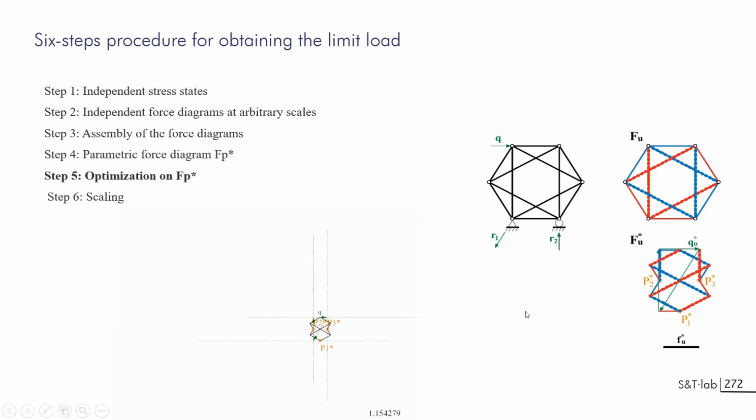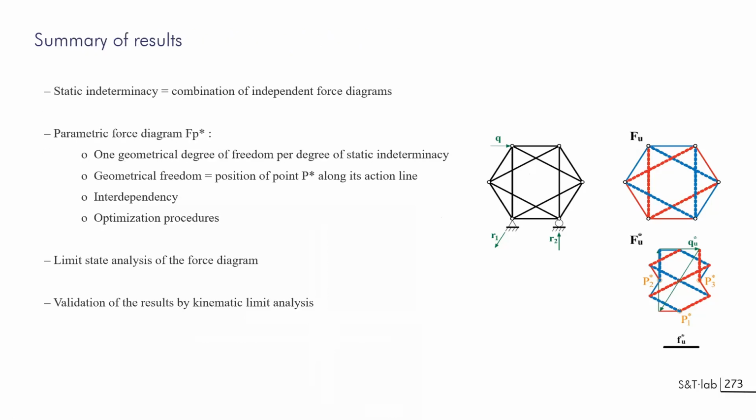So if you want to go to analysis, I make a difference with design. I will discuss design just after. If you want to go to analysis, you have to enter these different independent self-stress states and assemble them in a force polygon and run an optimization process to get what will be the final result. If you want to take this problem by the way of design, you can force several forces into the system, either by giving the thickness of the bar, or by imposing what will be the inner stress state, and that will drive you to another system that won't be a minimal, but that will be a choice that could be implemented as you want on the structure. And this is the question of design.